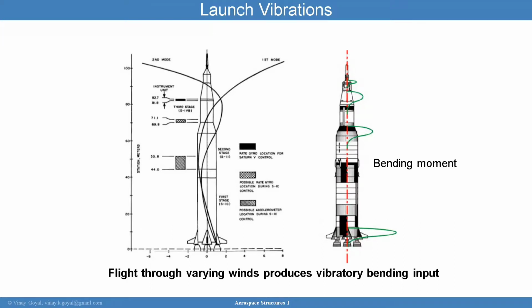Typically that is done to a level of 99/90 as an example. So we have a 99% probability that if you were to look at loads for a particular flight, those loads will not exceed the loads that you define, with 90% confidence. So not just the strength allowable is defined based on a statistical measure, like A basis or B basis, but the loads you're designing for are also statistically defined.